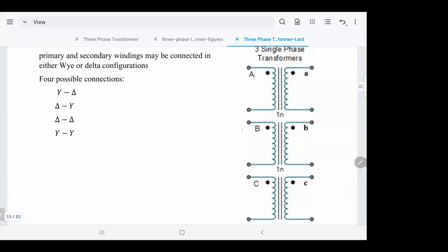Remember the primary and the secondary. Let's say that on the primary I'm going to apply the source, and on the secondary I'm going to connect the loads. So usually the current will come from the supply, will be in. I want you to remember this: the current will be in the dot, and then inside the transformer, out the dot. Then I'm going to connect the load, so usually the current will come out. If you continue, you'll find that inside the winding, the current is in the dot and is out of the dot.